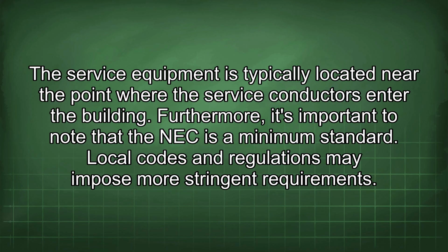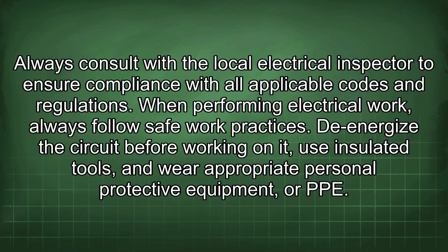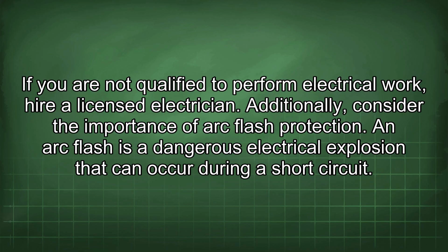Furthermore, it's important to note that the NEC is a minimum standard. Local codes and regulations may impose more stringent requirements. Always consult with the local electrical inspector to ensure compliance with all applicable codes and regulations. When performing electrical work, always follow safe work practices. De-energize the circuit before working on it, use insulated tools, and wear appropriate personal protective equipment, or PPE. If you are not qualified to perform electrical work, hire a licensed electrician.